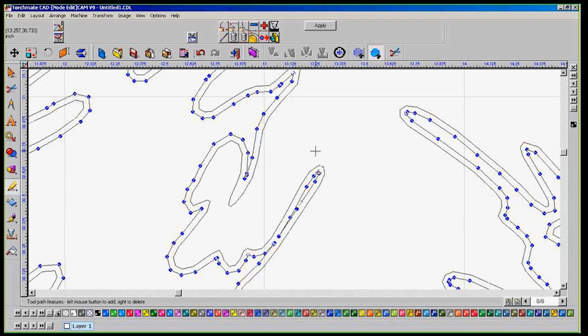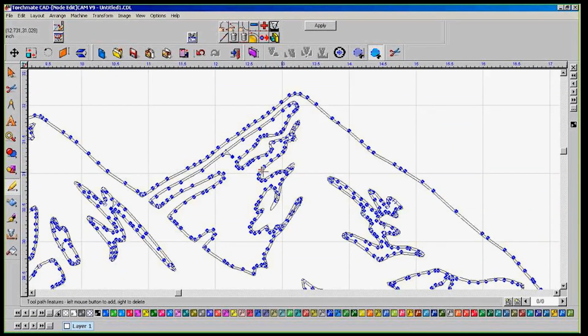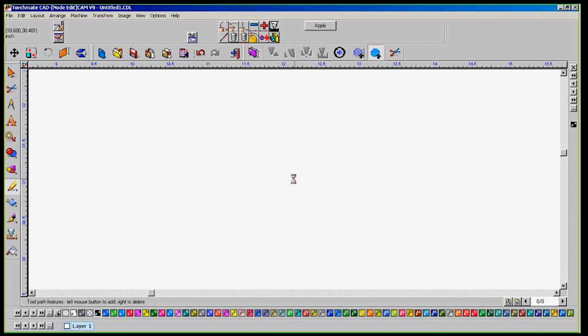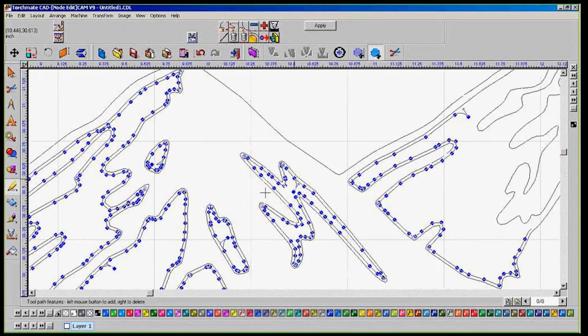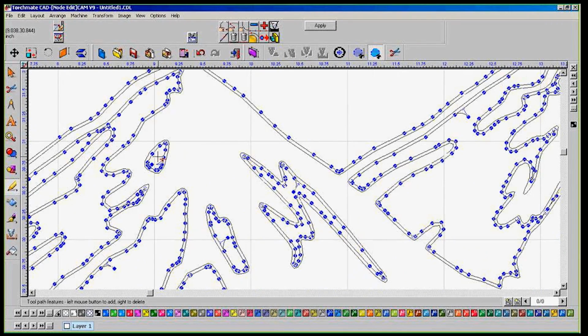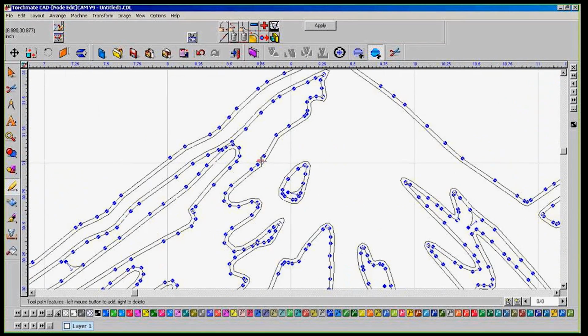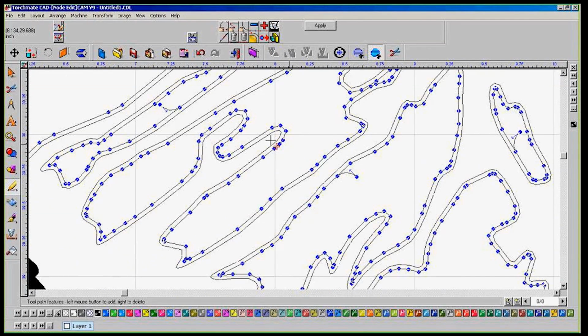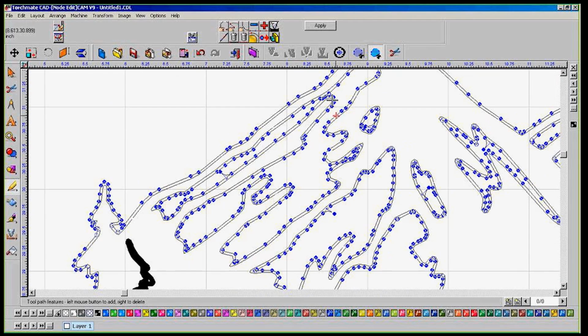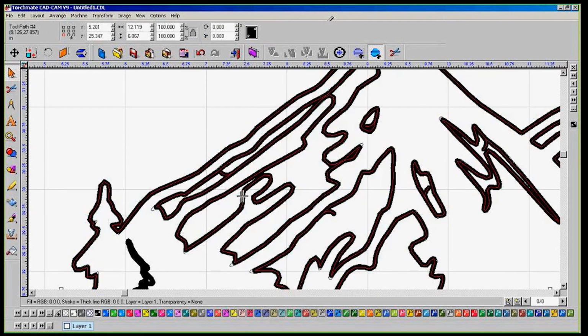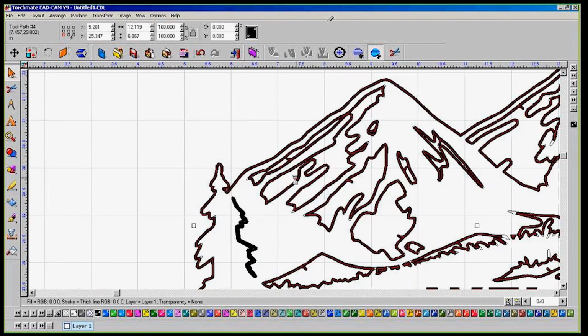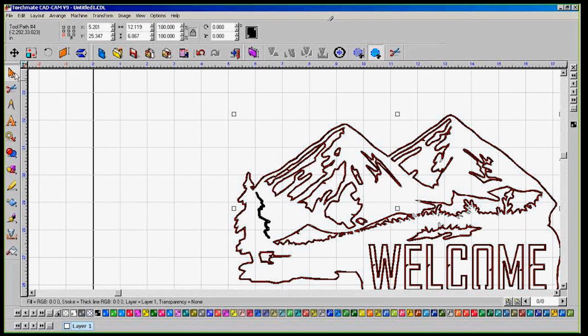As we can see. And now I'm going to generate the G-code out of CAD for our program to run it. So once I have everything selected, I made sure that it's at my 0,0 location based on my lower left-hand corner reference point. And then I'm going to go to Machine, and then Output. It brings us into our cut screen. Right now my post is set to AccuMove Imperial because this is designed to run and set up for our VMD system that runs AccuMove.